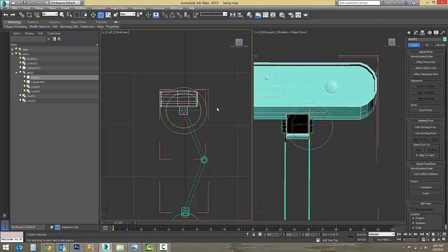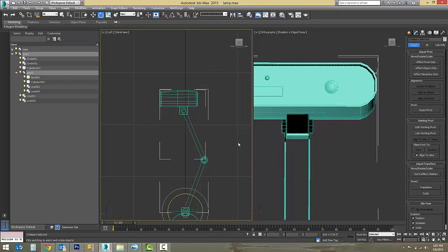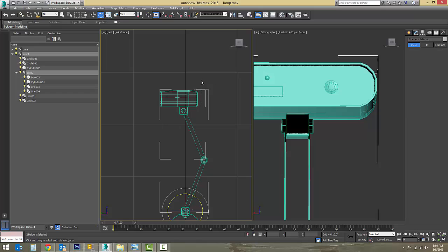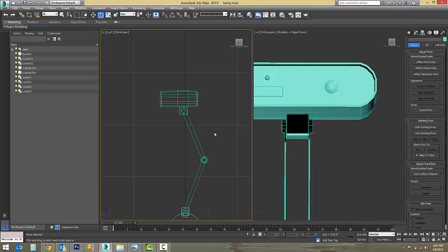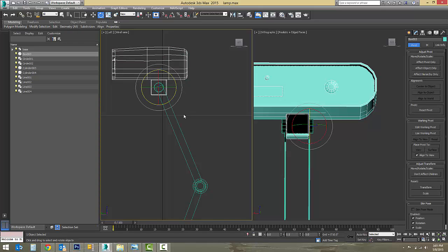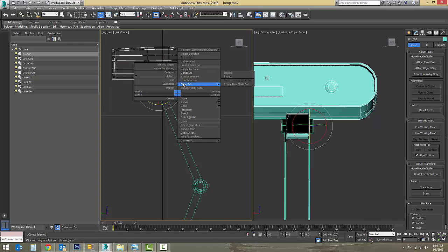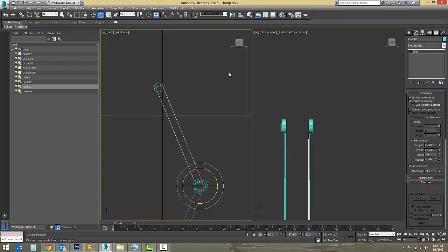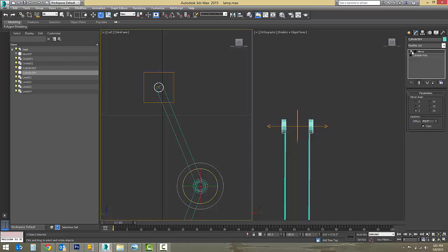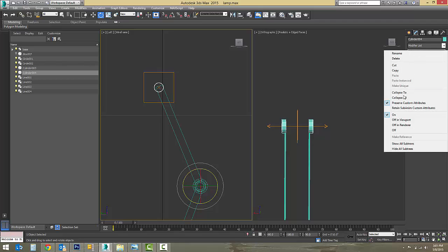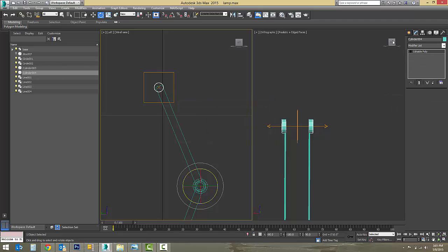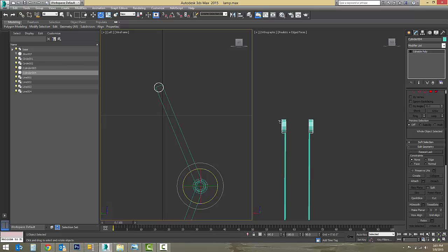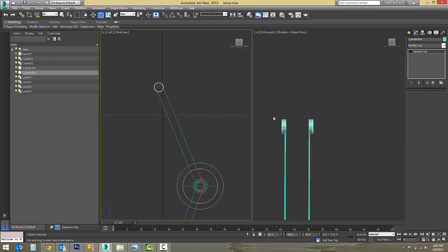If you don't like having these boxes, you can do the same attaching methods. You can delete the groups by selecting the pink squares, hit delete, and now I'm going to, for simplicity, say hide selection, grab everything above the waist, and this is still going to be a line, so you can't attach things from the line, and this is a mirror. So if we want to turn this into poly objects, we have to right-click on Mirror, say Collapse All, so that'll flatten it. So now before it was one object mirrored over, now it's just one object with two elements in it.